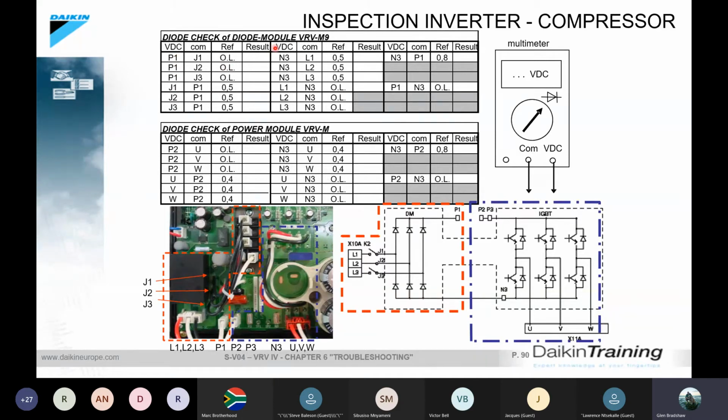Now, what I do is you can take this over here, and you can just make your own little table if you want, or photostat it before you went to site, and basically you test each item methodically on that line, and you check it. Yes, yes, pass, no, it failed. Hang on, one failure in this, the PC board fails the test. So you follow through that procedure, testing from P1 to J1.